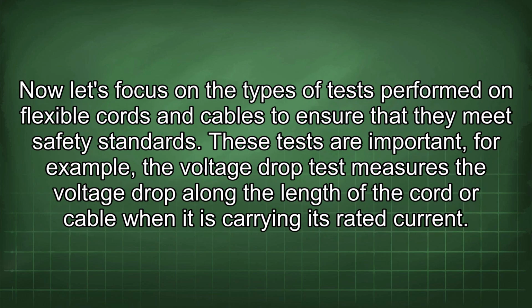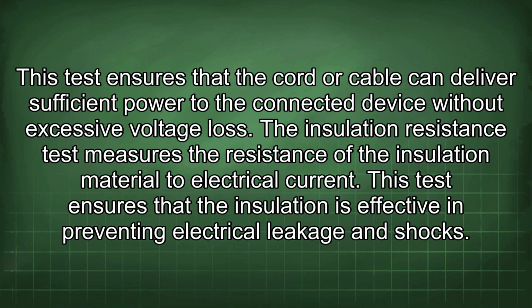Now let's focus on the types of tests performed on flexible cords and cables to ensure that they meet safety standards. These tests are important. For example, the voltage drop test measures the voltage drop along the length of the cord or cable when it is carrying its rated current. This test ensures that the cord or cable can deliver sufficient power to the connected device without excessive voltage loss.